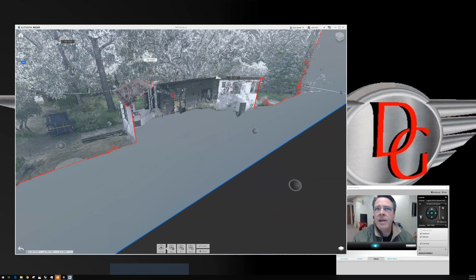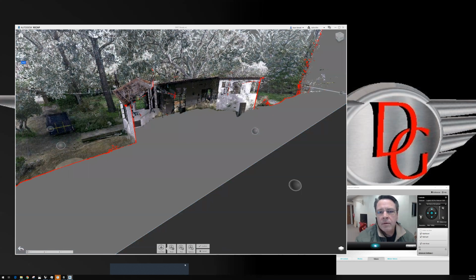A lot of the roof wasn't captured because we weren't able to actually grab that. A lot of times we'll fly the drone over the top of a structure if we want to get the roof, so we don't end up with the holes. We'll take the point cloud data from the drone flight and generate a point cloud of the roof line. Typically, when we do the inside, you'll see what looks like the roof, but it's actually the projection of the ceiling on that outer structure. So unless we shoot a drone flight, you won't get the interior ceiling and the roof. Let me zoom back out here real quick.